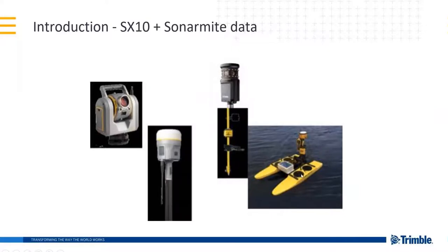Now, the Hydrone I was using is not autonomous. It's your regular remote control. The area I used it in was better for me because of the current. Depending on what you're going to use and how you're going to use it, that just depends on your personal safety out there. I do recommend when you're using any type of these drones in the water to please have a chase vehicle. Things do happen, current happens, wind happens, anything happens out there. You don't want to lose one of these out there. So that's my first precaution about doing this water work.